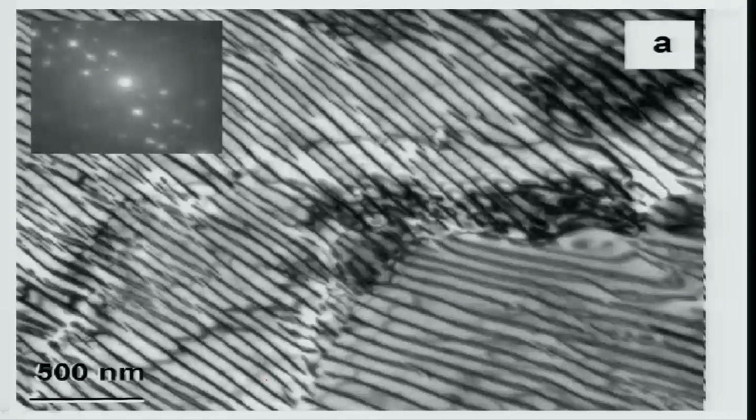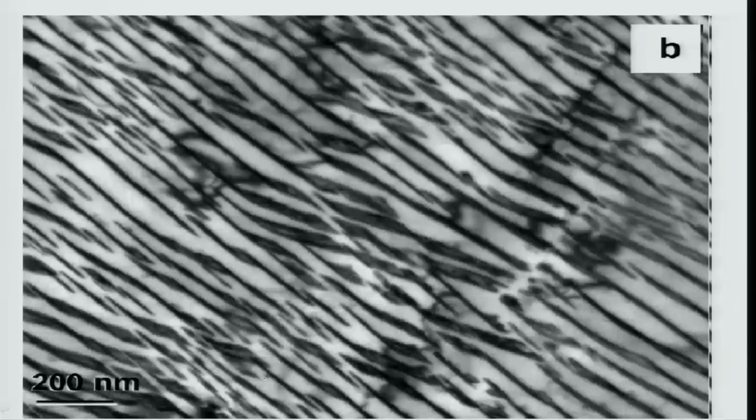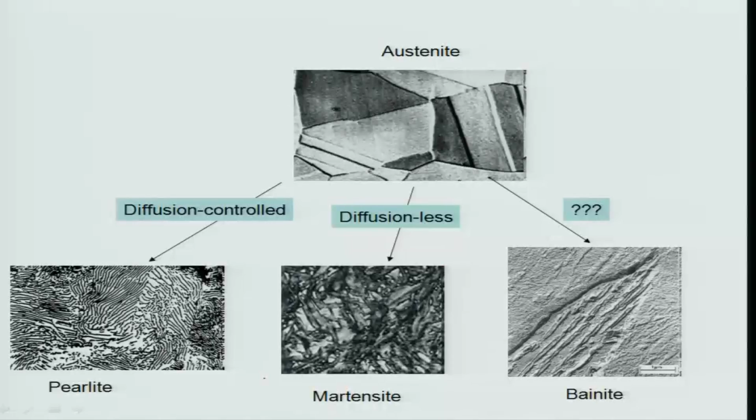You can see here these thicker ones are alpha phase, the black ones which I am pointing by arrow are basically Fe3C, correct. And this dimension is 500 nanometers. So, that means the distance between alpha and alpha is about a couple of 100 nanometers, and you can control this distance. By controlling this distance, you can control the mechanical properties. That is the beauty of this. And I am showing you many other pictures, because this is just like a eutectic morphology in the solid state.